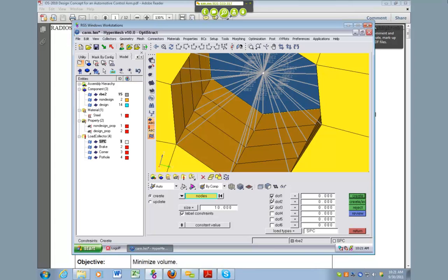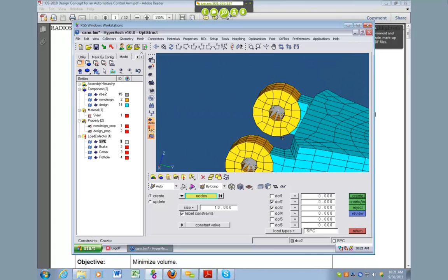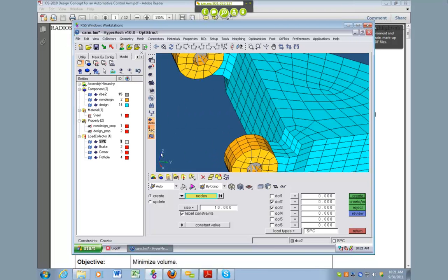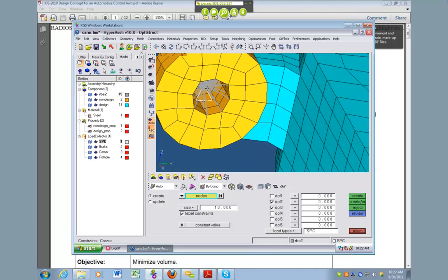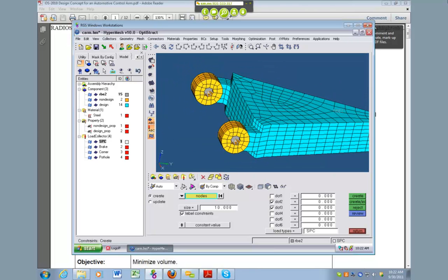just 2 and 3. So if you can see what's going on here, the x direction, which is this way, this side will be able to slide, it'll be able to move in the x direction, and it'll be able to rotate in any of the 3 directions, but it can't move in the y and the z. And so I'm going to click create, and now we have that second one. And so this setup makes a pretty good simulation of what a pin would act like, right?